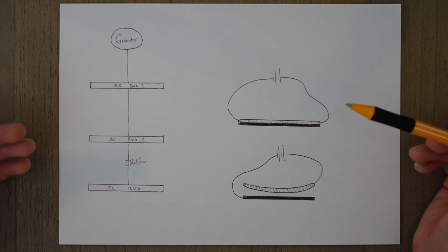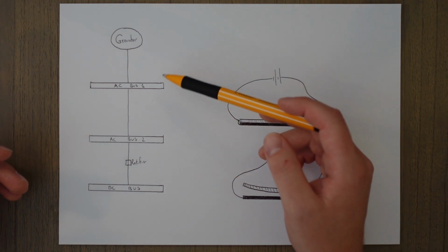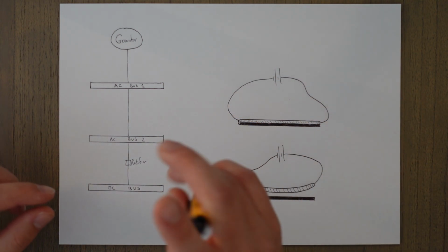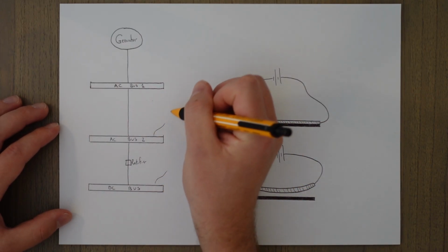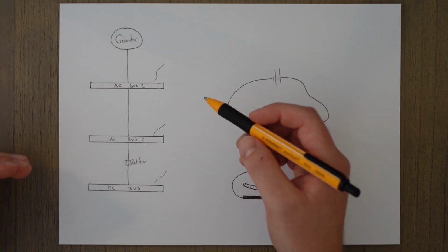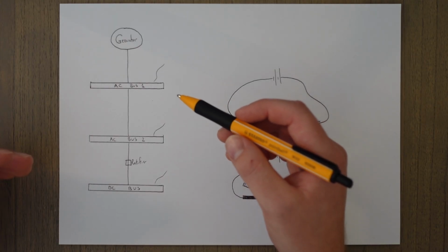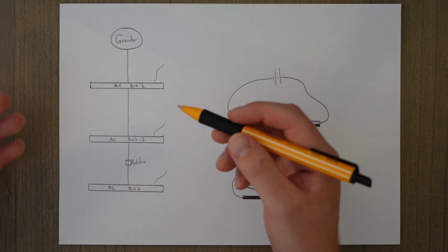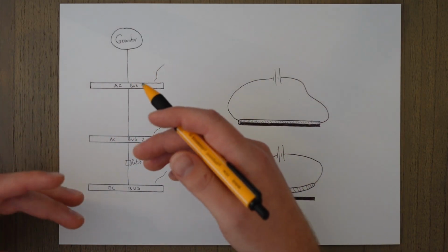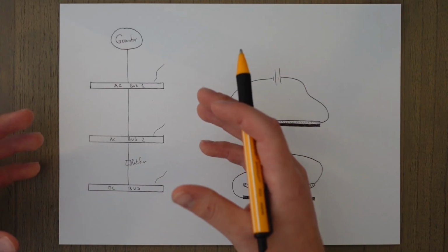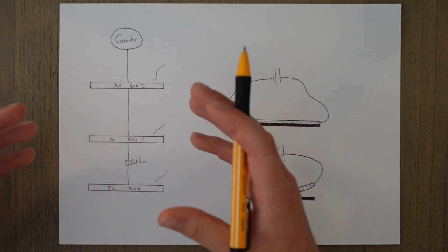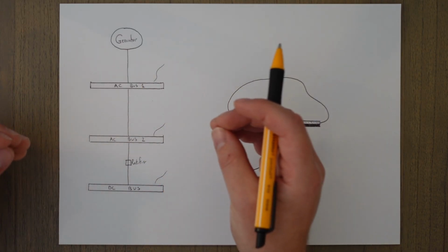But there is another important method called bus bars. I like to think of these as literally a bar of metal with wires to all the different systems touching it. And these systems will be wired to the bus bar in parallel so that if one of the components, like a light, fails, it won't cause all the other systems attached to that bus bar to fail as well. And the reason we use bus bars is that it's an easy way to group different systems together.